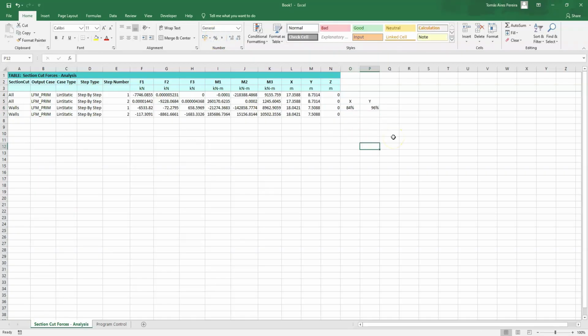This means it is clearly a wall structure. We don't even need to discuss whether they are dual systems or if there are different wall types, because the value is significantly higher than 65%. Now the question is, is it coupled or uncoupled?